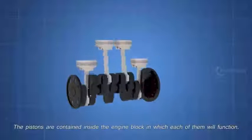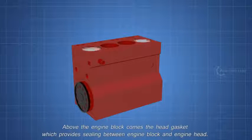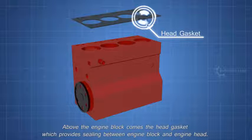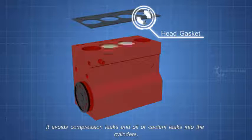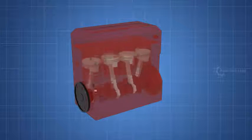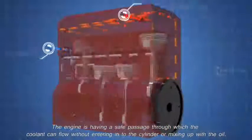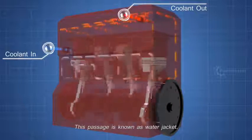Now, let's see how these parts work together. The pistons are contained inside the engine block, in which each of them will function. Above the engine block comes the head gasket, which provides sealing between the engine block and engine head. It avoids compression leaks and oil or coolant leaks into the cylinders. Above that comes the engine head. The engine has a safe passage through which the coolant can flow without entering into the cylinder or mixing up with the oil. This passage is known as the water jacket.